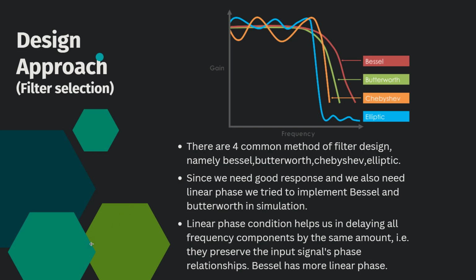As you see at 600 millihertz, the output was around 840 millivolts, and as we decrease the frequency, at 500 millihertz it was around 760 millivolts, and at 200 millihertz it went down to around 300 millivolts. So as you can see, when we go below 0.5 hertz, our signal starts to attenuate.